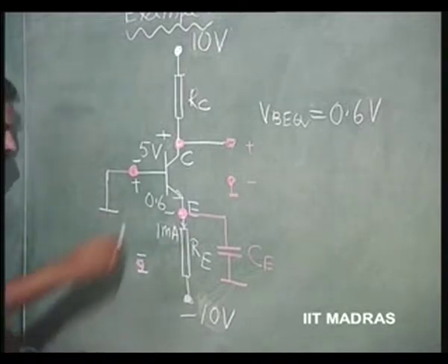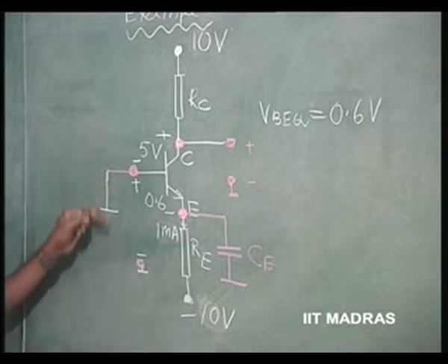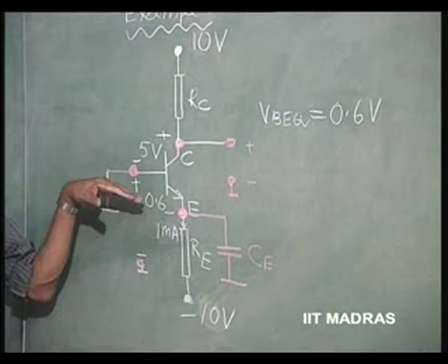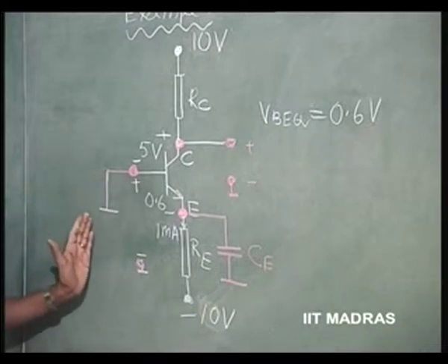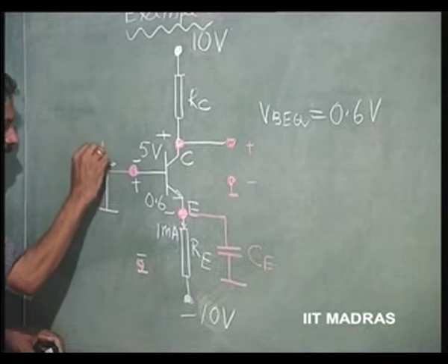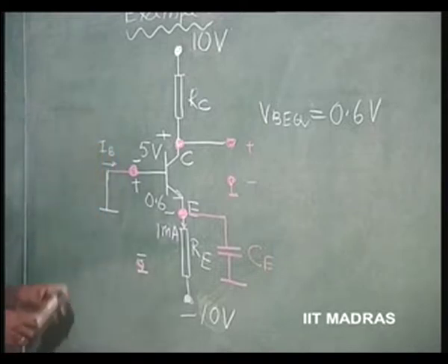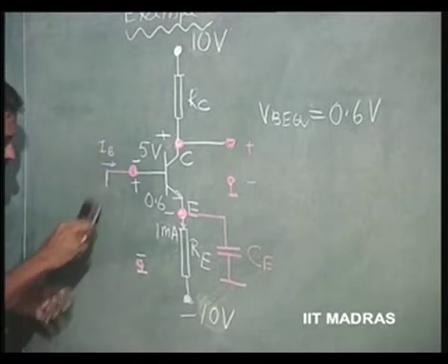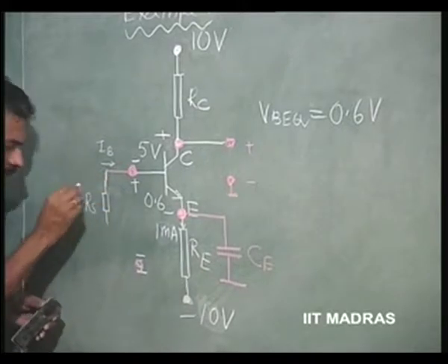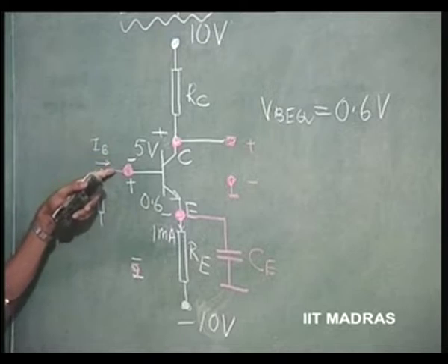So, basically we have, as far as DC is concerned, this having 0 DC potential, otherwise the base current will also flow through the source resistance. Please remember, if the base current is IB and there is direct coupling, then through RS the base current will flow.